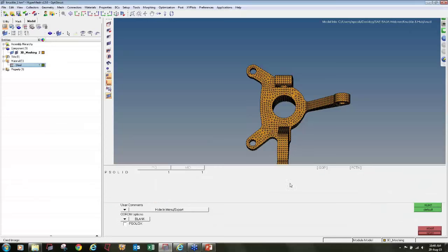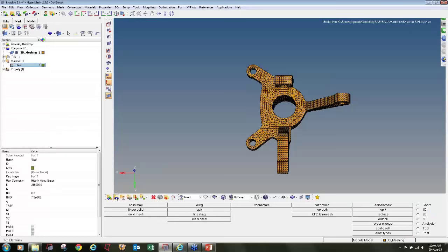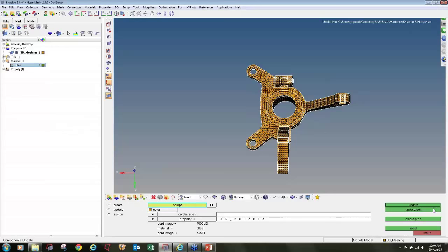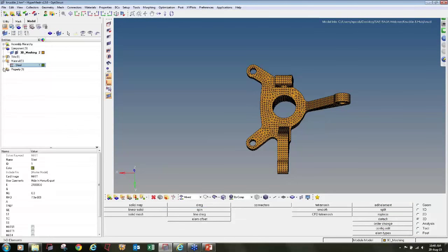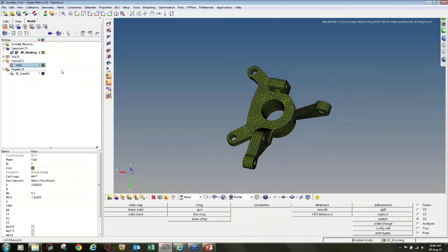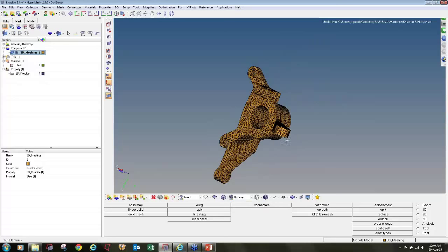If I click on create edit, there is nothing to provide as input here. Then components, update the component with proper property and material. So my material, property and component updation is correct. So I will quickly check with the elements color. I got a property color on the elements, material color on the elements, my components color on the elements. So I quickly check with this.